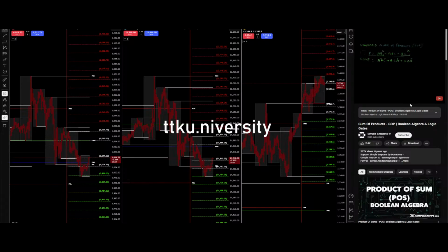Let's take an example. Okay, so I've written the question on the screen. Now as you can see, in this product term we are missing the term C, and in this product term we are missing the term A. So to convert this sum of product expression to a standard sum of product expression, we need to introduce these two variables in these product terms. So how do we go about it? Let's first write down that product term over here separately.